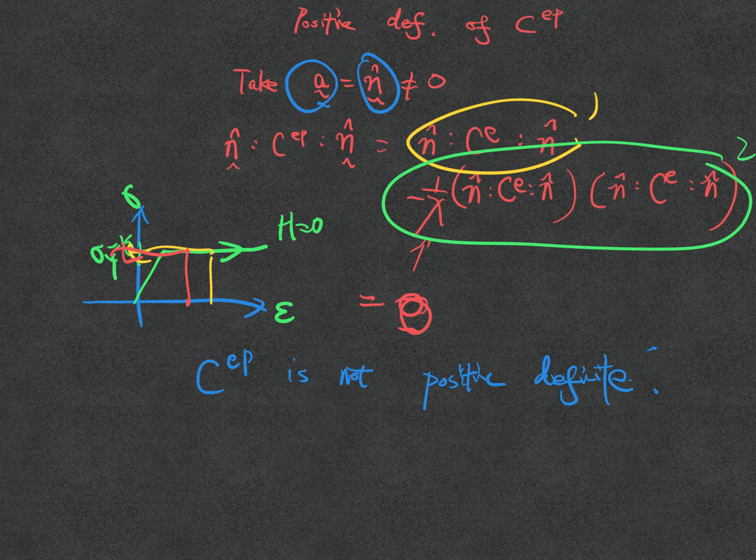If stress and strain are 1-to-1, I should be able to know one and then map it to the other one. Okay? Because the inverse exists. Okay? But here there is no inverse. If I have a curve that looks like this, I can view this as x and this as y, but if I look at y and figure out what is x, I can still find it. If I know x, I can know y, or if I know y, I can know x. Okay, I just map it in a different way because the inverse exists. Here the inverse doesn't exist for a very simple reason.